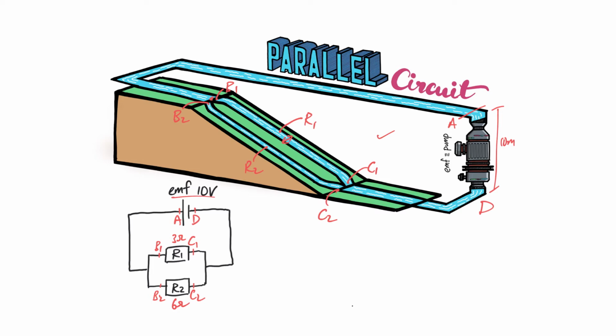These are things that you can relate to. Next, let's go through the 3 rules. Let's start with the total effective resistance. Maybe let's recall, if it's a series circuit like the previous video, let's say this is R1 and it's 3 ohms and R2 is connected in series 6 ohms. To find the total effective resistance, you just need to add both of them up, 3 plus 6, that will be 9 ohms, and you realize that the total effective resistance will actually be much higher.